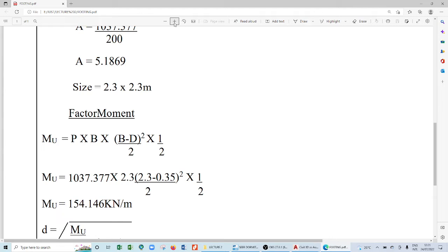So you have to get what they call the critical punching area. If you look at this, the critical section of that column, if there is a moment, it will break like that. Are we getting it? Let's say there is a moment on this other side. So I expect the column to break along this line, making the footing break off from this point here. If this column is clearly this way, there will be a punching area at this point, breaking off from here. So if this is the breaking area, we need to get that. So remember, if this is here, how about the center?